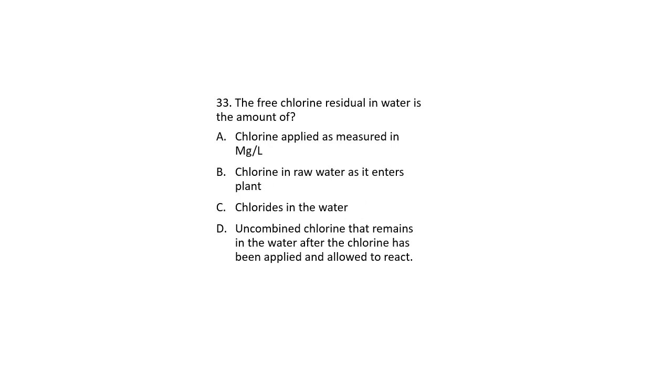Free chlorine residual in water is the amount of chlorine applied, measured in milligrams per liter; chlorine in raw water as it enters a plant; fluorides in the water; or uncombined chlorine that remains in the water after the chlorine has been applied and allowed to react. The answer is going to be D, the uncombined chlorine that remains in the water after chlorine has been applied and allowed to react. Breakpoint chlorination.